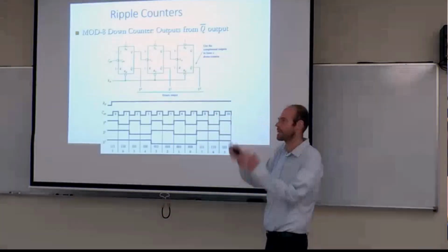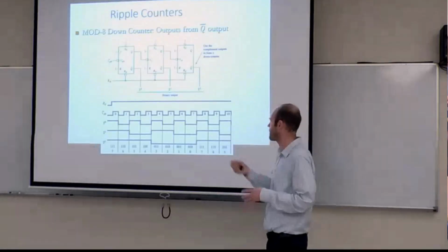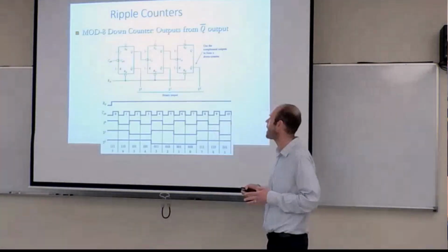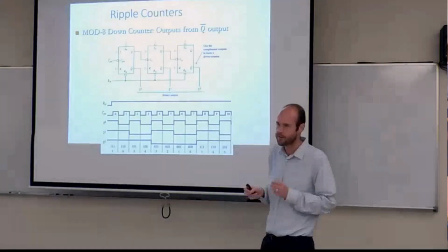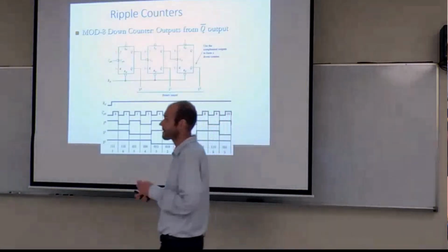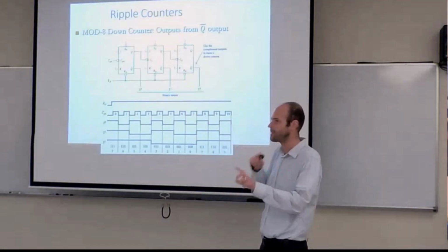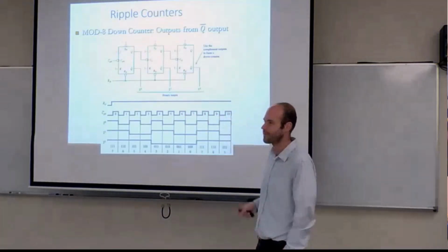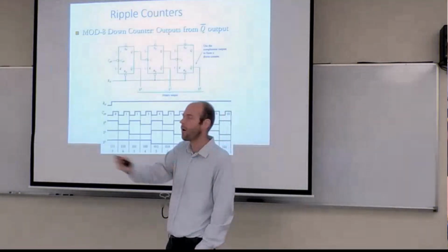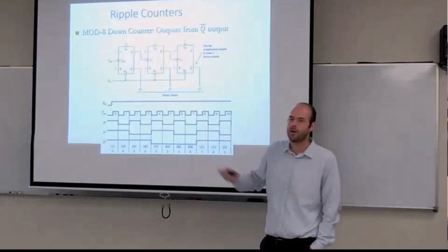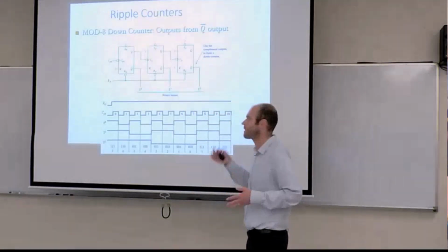So if you did K-mapping to figure out a sequence of logic, and we'll go into how to do that with this type of system a little while later, the mixing of rising edges and falling edges is very uncommon, because that behavior is not all mathematically connected, and you disjoint some portions of your system. So no, you don't mix rising and falling edges. Typically, you have all falling or all rising, and then you have all active low logic or all active high. You don't mix and match on one system.